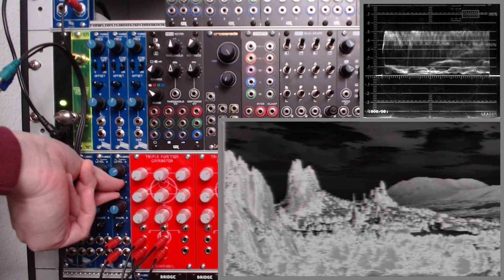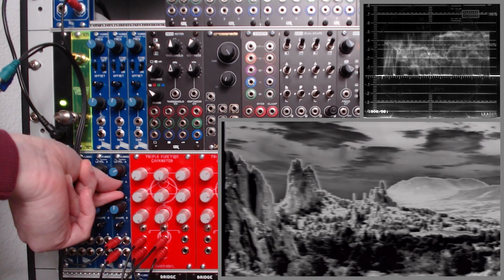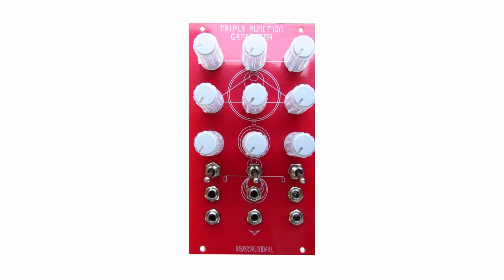You can control the relationship of tones within the image or within the signal, which is something you can't do with proc. Proc is just going to give you the ability to stretch the dynamic range or bias that signal up or down, but all the tones within that image are going to maintain the same relationship to one another. But VU005 is going to let you change the contrast curve. And that in turn will allow you to dial in exactly the contrast that you need in order to get the result that you want from some other module. And the example I'll show today is the Sine function generator.